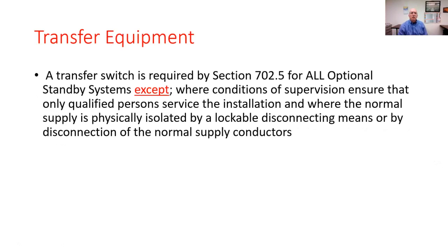So the transfer switch is required by section 702.5 for all optional standby systems, except where conditions of supervision ensure that only qualified persons service the installation, and where the normal supply is physically isolated by a lockable disconnecting means, or by disconnection of the normal supply conductors. Well, I don't know of many homeowners that could fit that qualification.